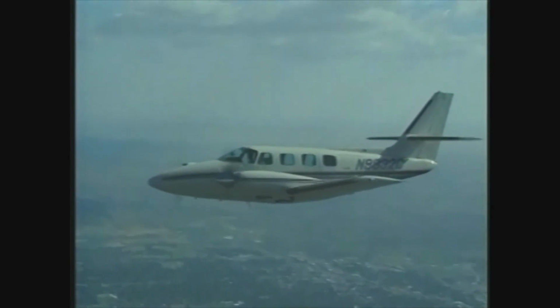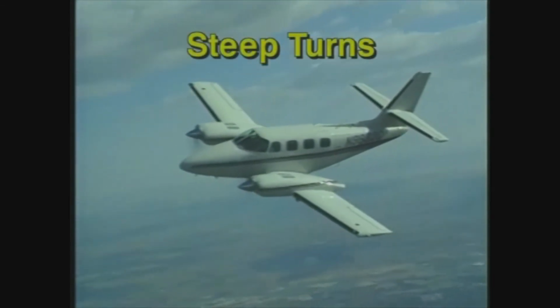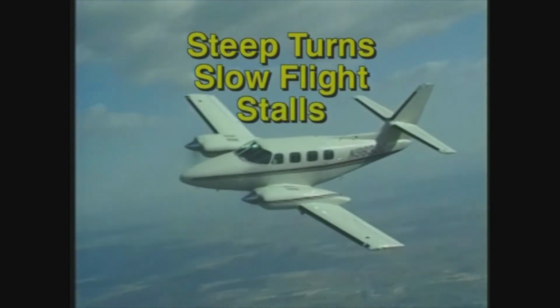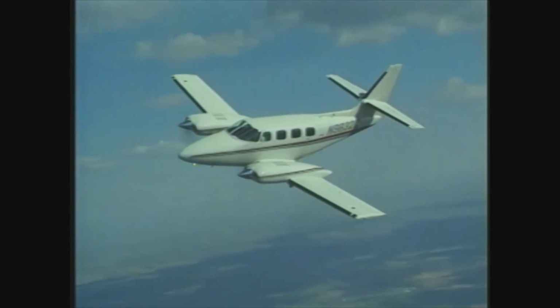To add a multi-engine rating to your certificate, you must be able to perform several maneuvers, including steep turns, slow flight, and stalls. These are designed to help the examiner judge your ability to safely control the airplane. Before any maneuver, always check the area using clearing turns.